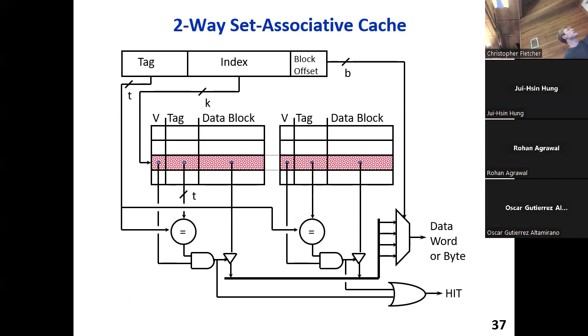The two red speckled cells are the 2 slots in that bin that we're going to read out. We're going to read them both out. We're going to check our tag as it comes out with the data, and we're going to do the same column decoder, quote unquote, style muxing to get the word that we want, along with checking whether there's a cache hit or miss, and we get our data out in exactly the same way.